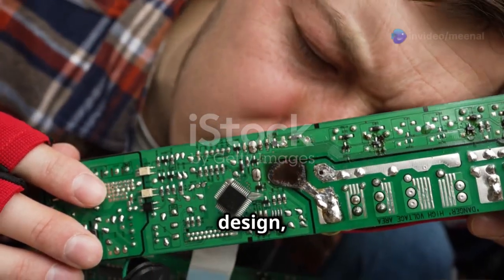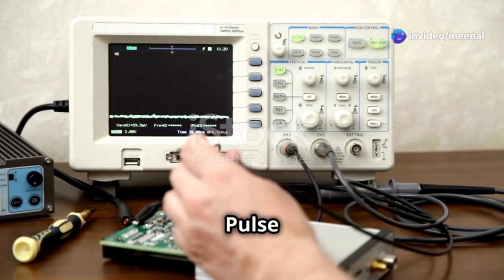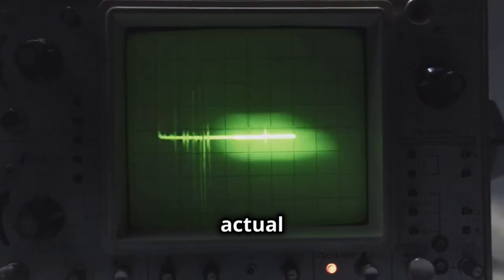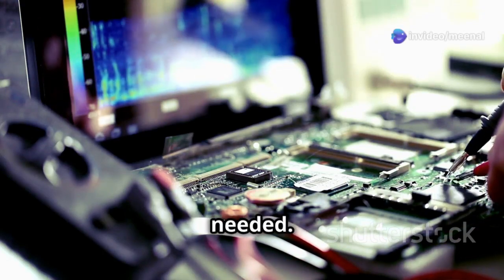Even with careful design, reset circuitry can have issues. Pitfall 1. Improper reset pulse width. Double-check the minimum reset pulse width requirements in datasheets. Use an oscilloscope to measure the actual reset pulse width. Adjust timing components or IC settings if needed.